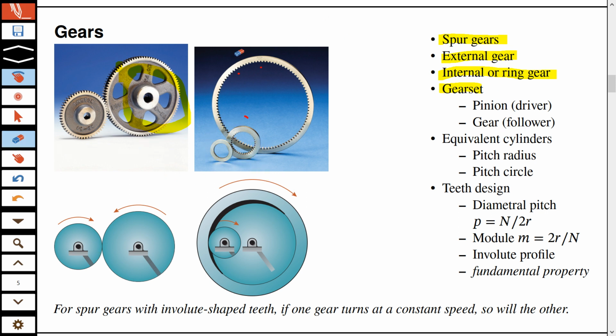So in gear sets you follow a certain terminology. Because you want this to transmit power, one side or one gear will be connected to the power source, like a motor, or yourself. Maybe you are driving yourself. So that gear is the driving gear. It's actually called the driver, and it drives this one. So you can call this the follower.